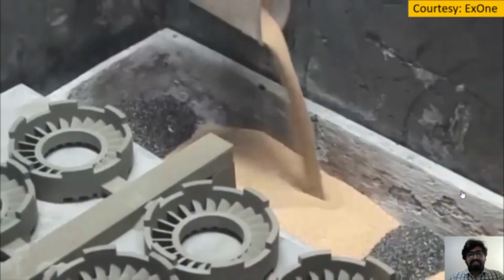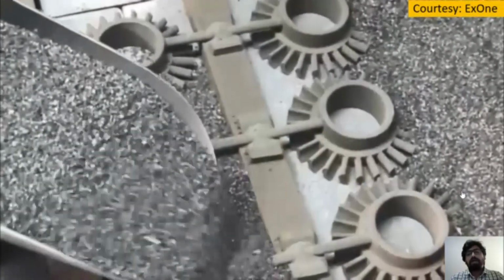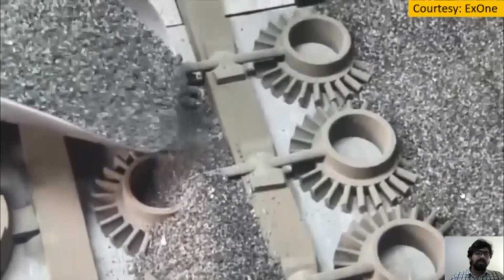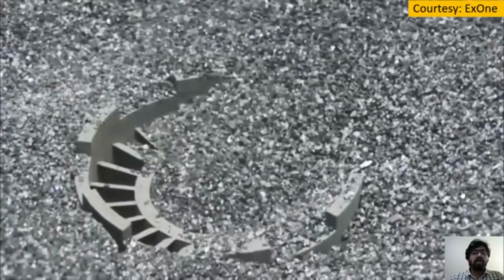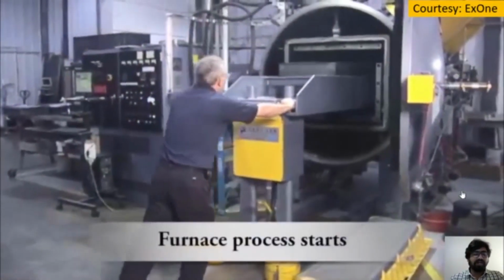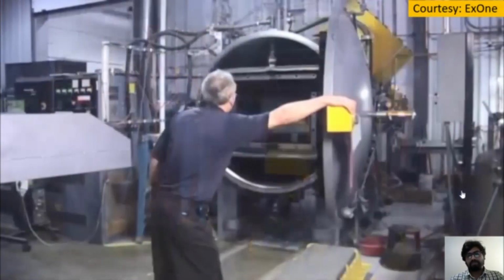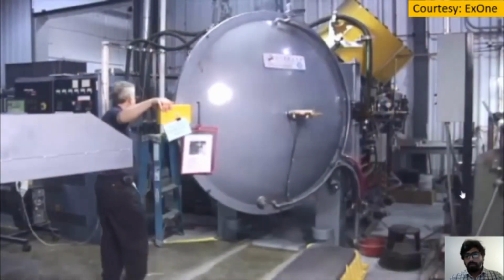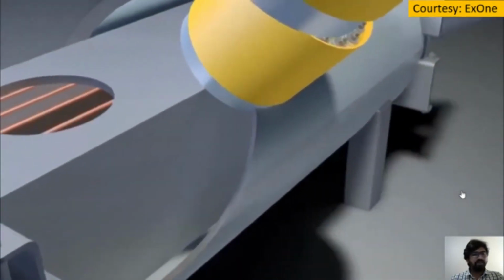After making this arrangement, the entire chamber is kept into a furnace where, when the temperature rises, the copper powder will melt and it will get infiltrated into the voids of the parts and the gate. So as you see here, the entire arrangement is now transferred into a furnace where the temperature will increase.